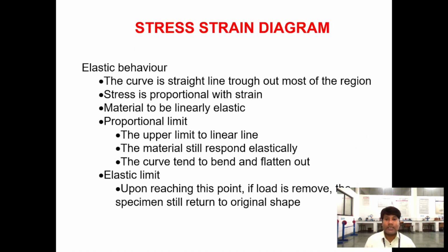That is elastic behavior. The curve is a straight line through most of the region. Stress is proportional to strain, and the material is linearly elastic. Proportional limit is the upper limit of the linear line. The material will still respond elastically.